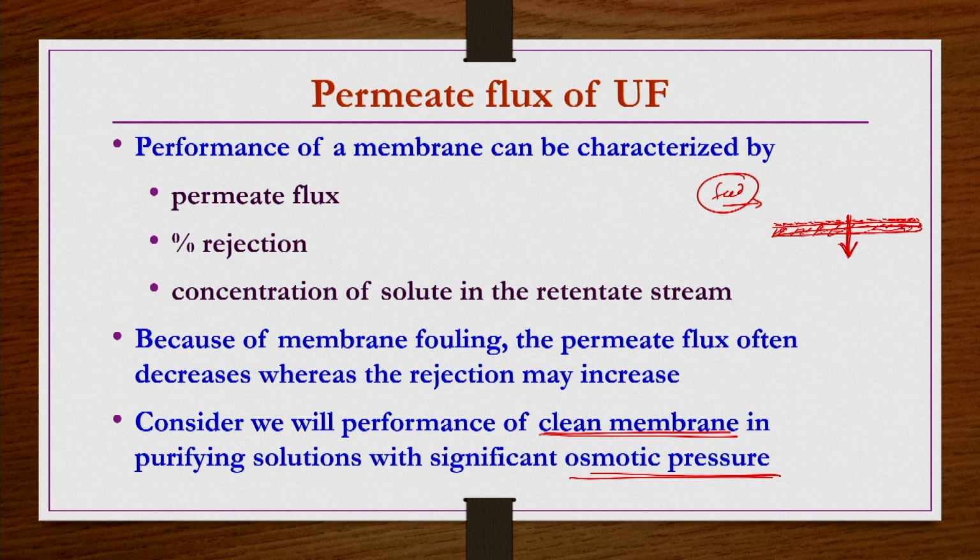Now, what we consider? We consider the performance of a clean membrane used for purifying a solution having a certain amount of osmotic pressure. Okay. So, this osmotic pressure is a function of concentration, as we understand. As the concentration of the solute increases, the osmotic pressure of the feed solution increases. Okay. So, then accordingly the correction has to be made in the performance. All those things we are going to see now here.